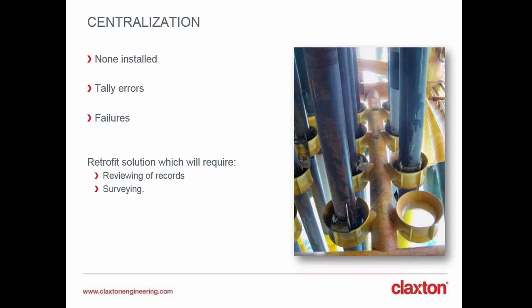Another problem is also failure of the original centralizers, as I mentioned before. The failure could be for a number of reasons. It could obviously be a mistake in the original design, but it could also be that equipment was damaged during installation or during its life, or it has simply exceeded its design life. It's not uncommon on some of our older platforms. Equipment was originally designed for 15 years and has far exceeded its expected life. So it just needs some attention.